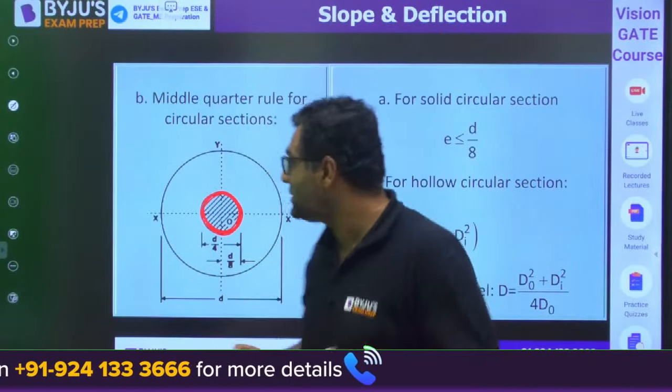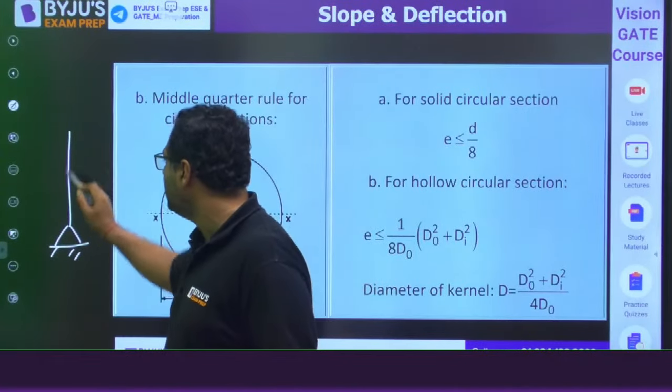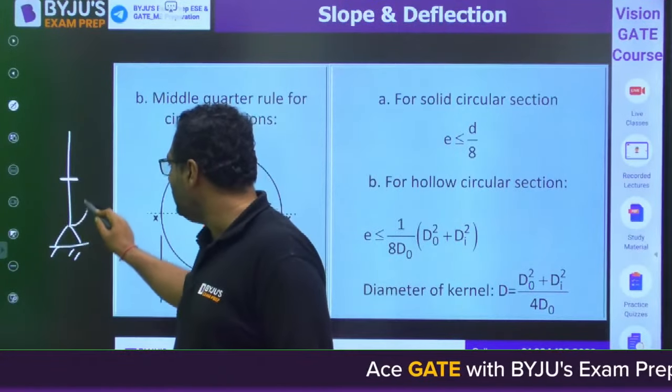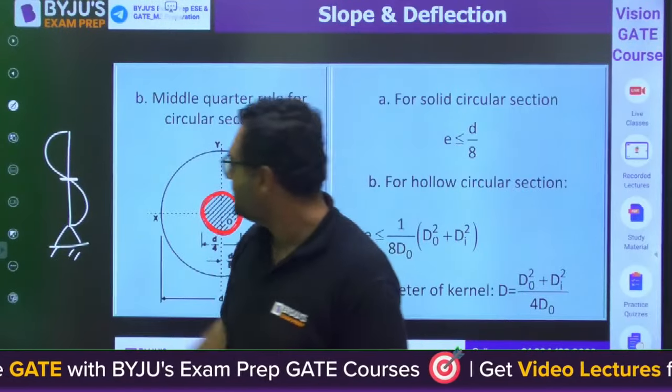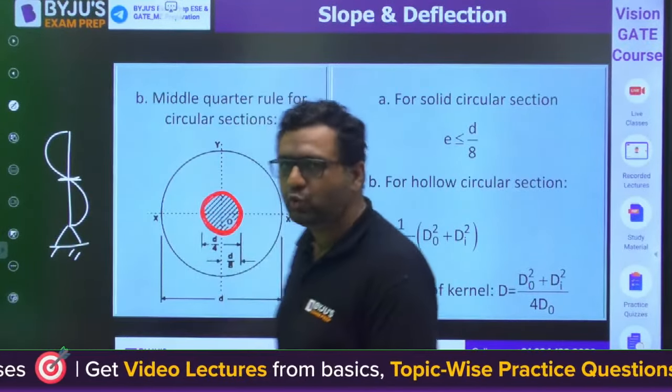Vineet Shah, because it is not mentioned. Only when it is mentioned that we have some clamping element here can you have an n value of 2 or 3 like that. They never mention this clamping element, so we consider n equals 1 only.